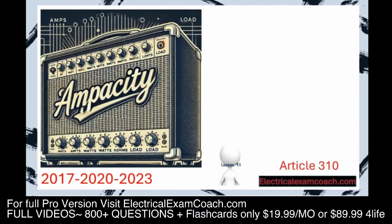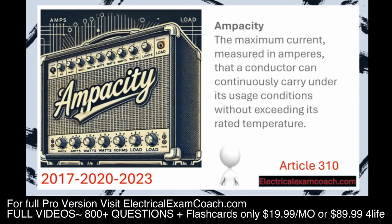We're going to be in Article 310, and we're going to be learning all about ampacity. Ampacity is the maximum current measured in amperes that a conductor can continuously carry under its usage conditions without exceeding its rated temperature. Everything that we're doing in this program and out in the electrical field is to protect first the people and then the equipment.